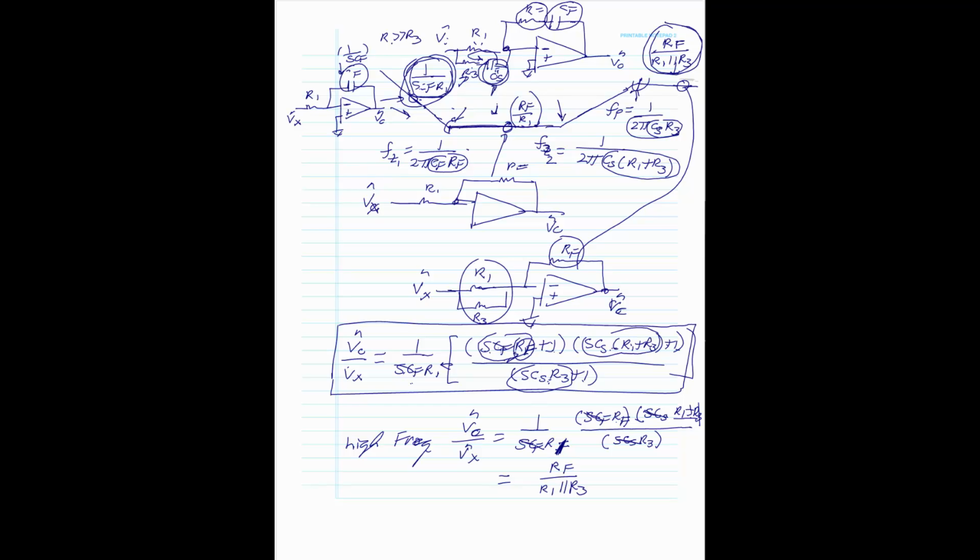So ultimately, the phase is going to start at minus 90, back up, back down again. This is going to be the phase of the circuit, and you'll see it when we simulate it. It's going to start at your minus 90 degrees. It's going to start boosting up, depending upon where the pole and zero locations are, and then it's going to start backing down on you again, because of the higher frequency pole.